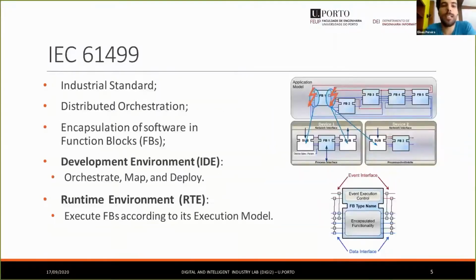Focusing on the IEC 61499, that standard is composed of two different components, the development environment and the runtime environment. The development environment is basically where the developer orchestrates his pipeline of tasks. Each task that you have here is a function block, which has an event interface, where the events trigger different functionalities in that function block, and a data interface.